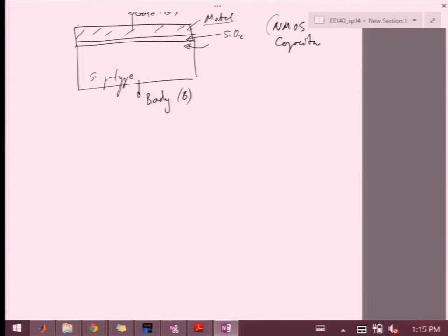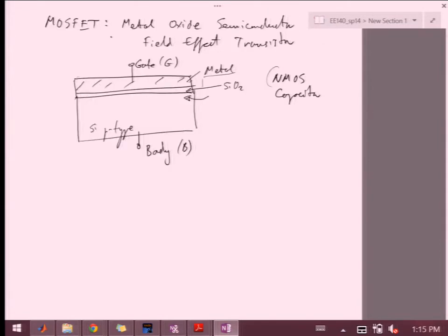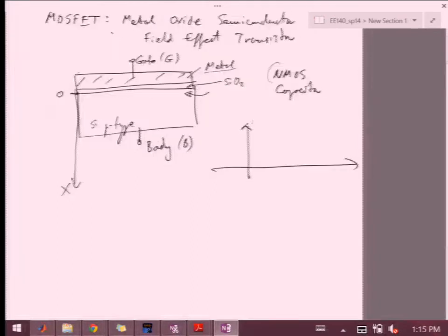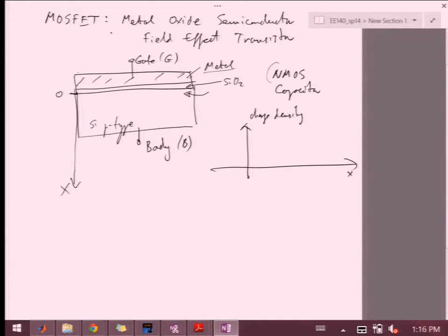So if we take a look at this gate and then plot the charge concentrations, which is what we're all interested about, if I label this as the x-axis starting from coordinate 0, and I then plot the charge density as a function of x, then if I have the gate as positive, I'll have some charge in the metal after this, which is Tox, the oxide thickness.